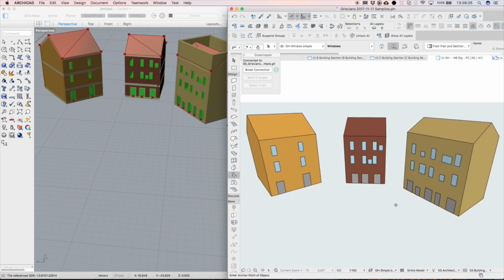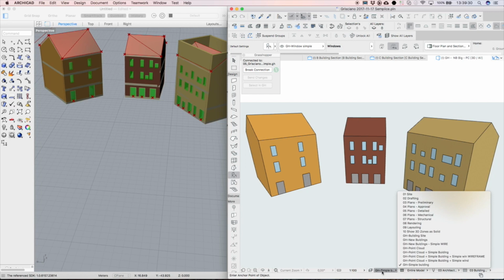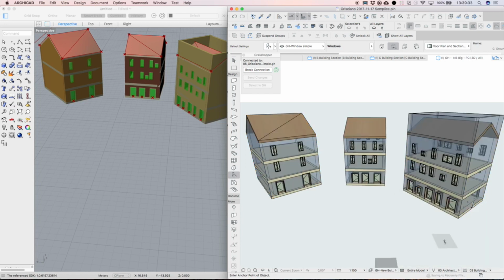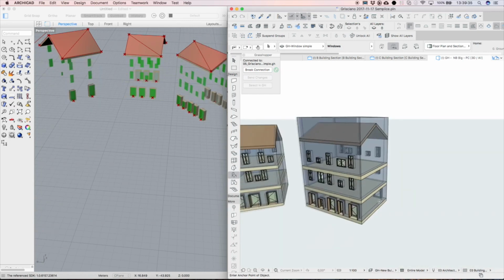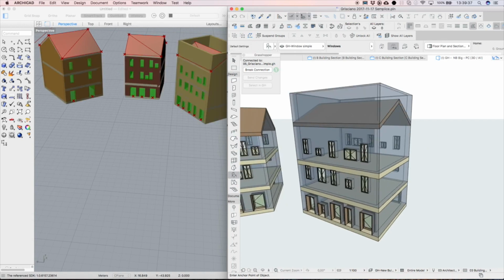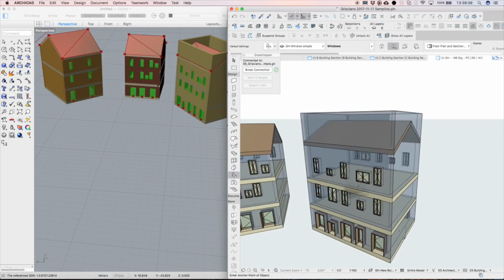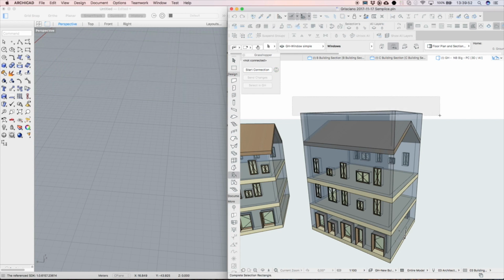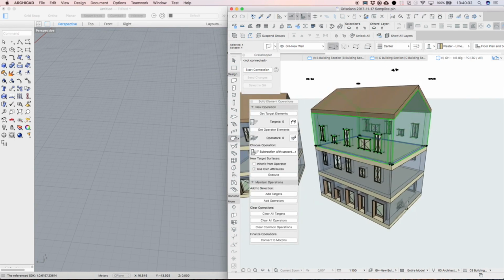Let's switch to the ARCHICAD model presenting the final model that contains real walls, roofs, slabs, windows, and doors. This BIM model was created using the Deconstruct and Extract settings features of the Grasshopper ARCHICAD Live Connection tool. We deconstructed the Morphs in Grasshopper and used their acquired properties to create ARCHICAD wall, slab, roof, window, and door elements. We'll trim the top of the gable walls to the pitched roofs. Please notice the results of this operation in the 3D window.